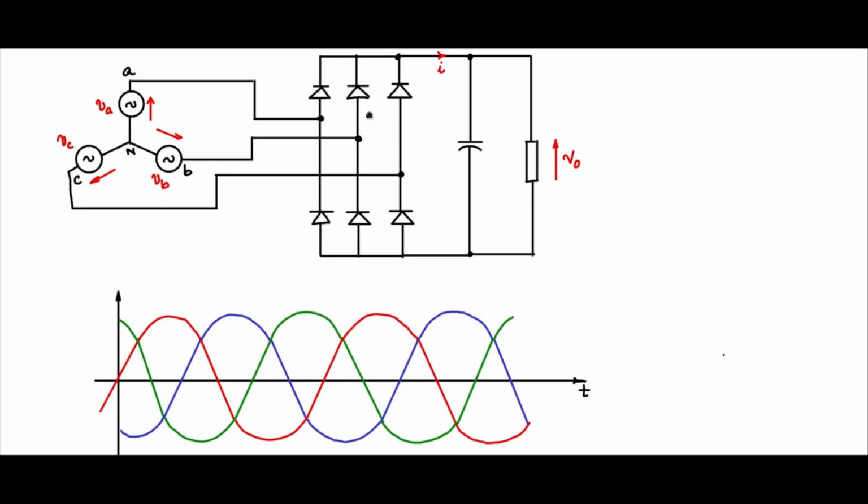And now when it passes through the rectifier at this node, across this node, if the capacitor were not there, you will see that this will be the rectified waveform, folded back. So I will show that in dotted. You will see that these bottom portions will get rectified in this fashion.